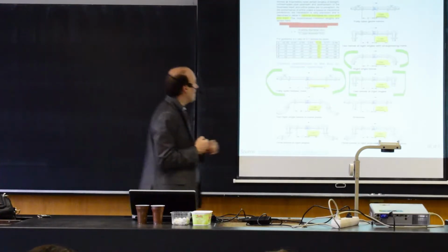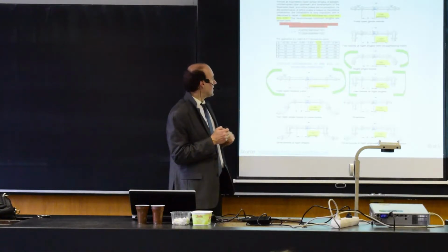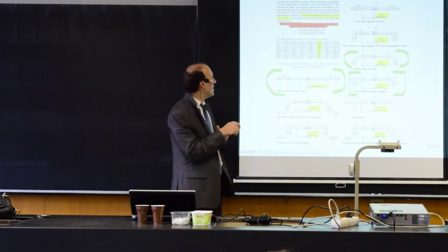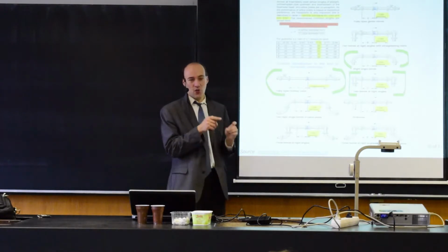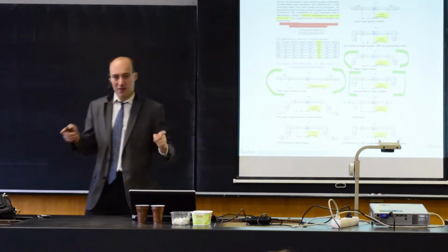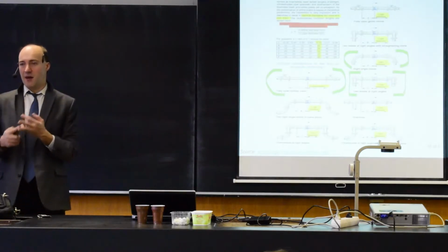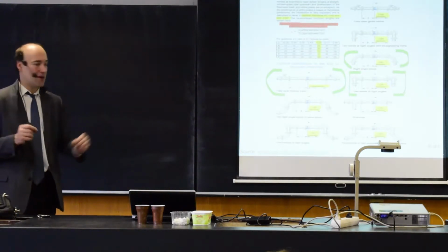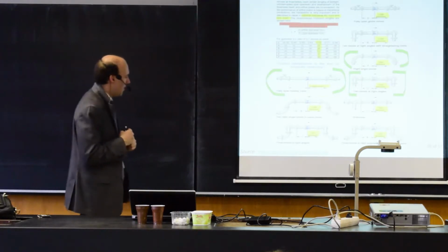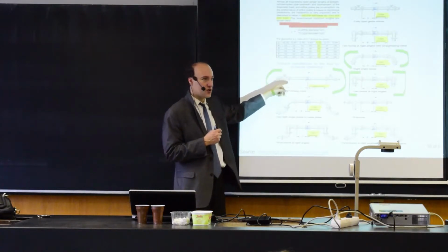So let's say I have the ratio, let's say 0.7, just a random value. And for the case of the straight pipe in front of the orifice plate, you see here I need to keep at least 20 pipe diameters in front of the orifice plate. So in these 20 pipe diameters, I cannot install any walls, any flaps. There can't be any bending at all. It just needs to be a straight pipe so that you develop the flow profile in front of the orifice plate. And if you look in this table, this is the shortest distance for this straight pipe.